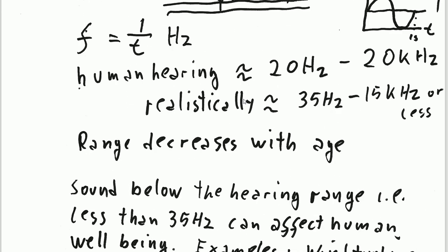To be fair, the old telephone system, when you listen to that, the frequency range is only about 2 to 2.3 kilohertz. I think it goes from about 300 hertz to 3.4 kilohertz, so it's about 3 kilohertz. It's very, very limited. And then right in the middle of the old analog telephone system, they had some bands which were cut out and just used for signal transmission. For billing and stuff like that, they were putting some signal through.